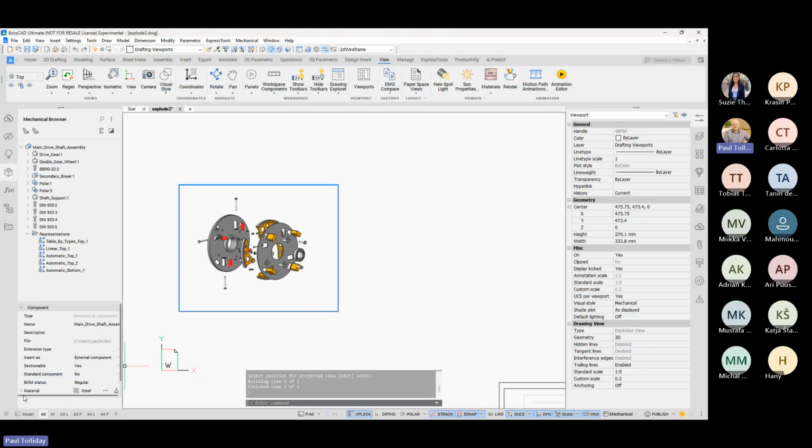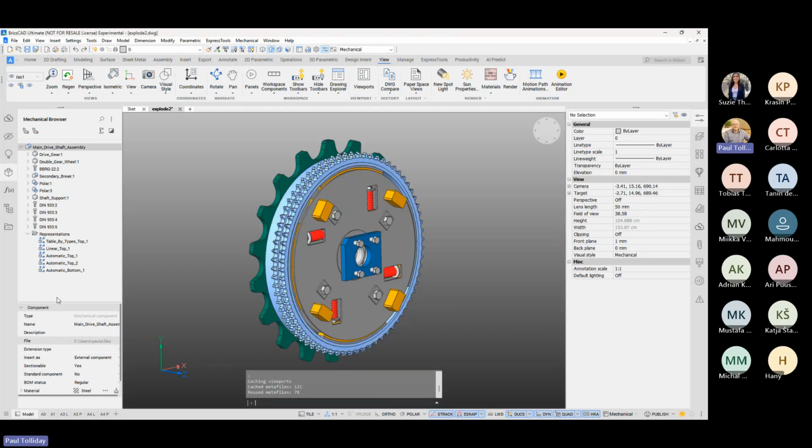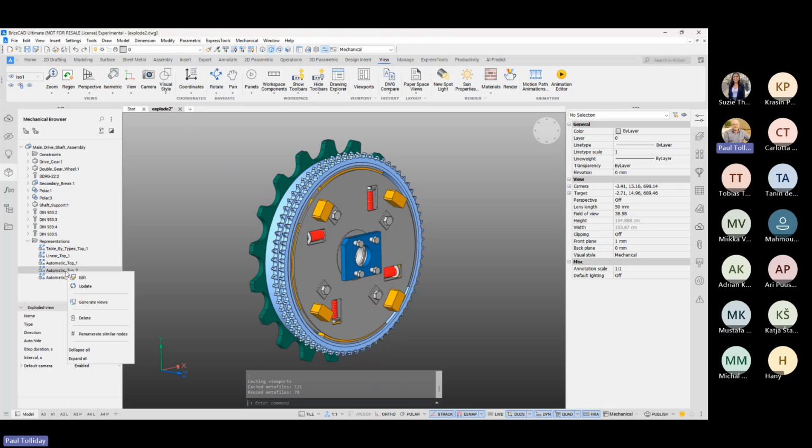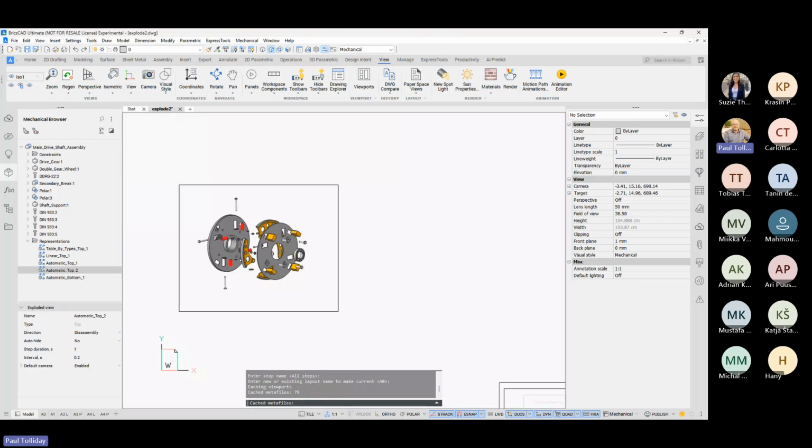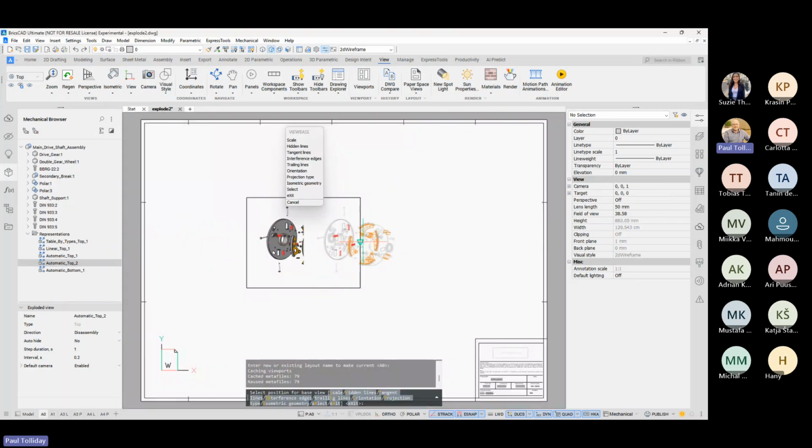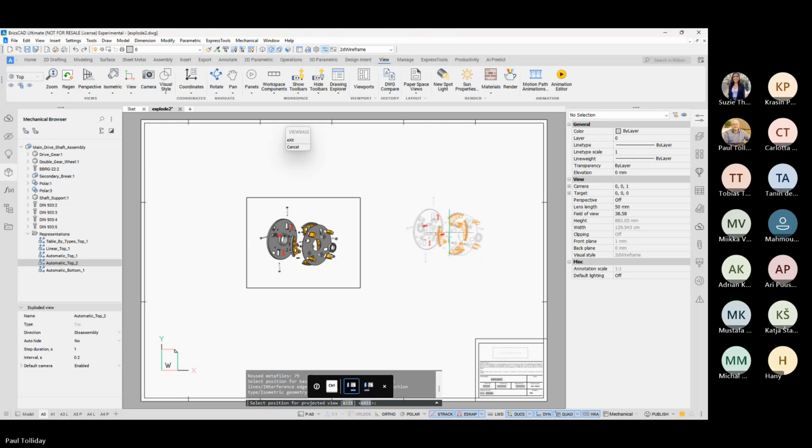So we've got that view placed. And what we can now do is come back and we can place the same view again. So generate the views on the same drawing sheet. And what we're going to do is just go from the midpoint of that line. So we've got our snaps already working for us. So we can track that across. Like so. Again, that will render, take a few seconds.